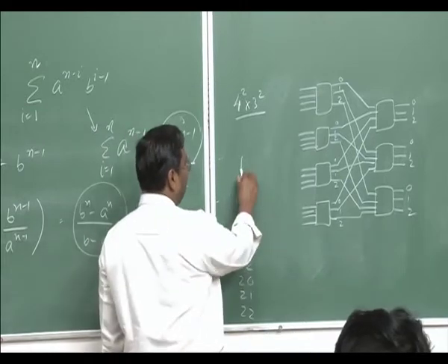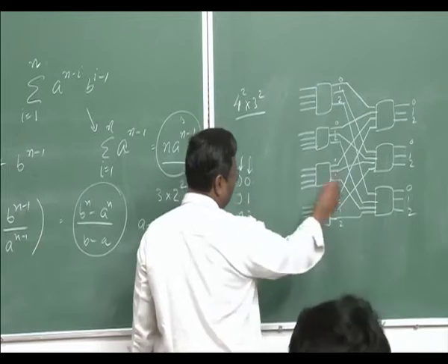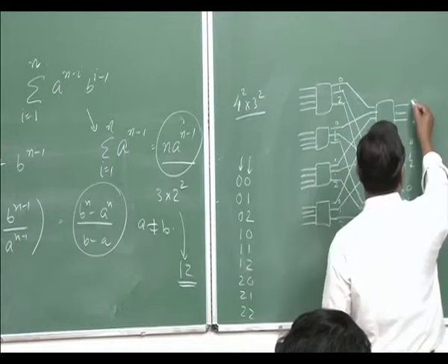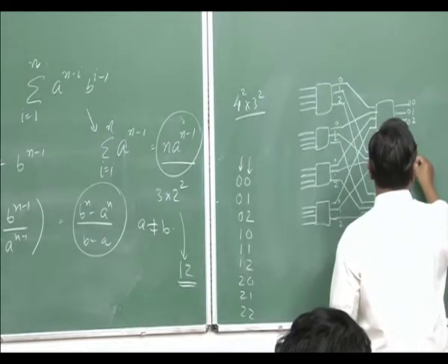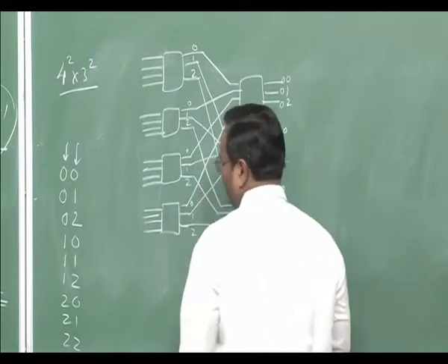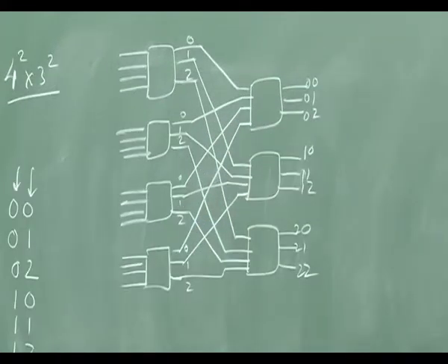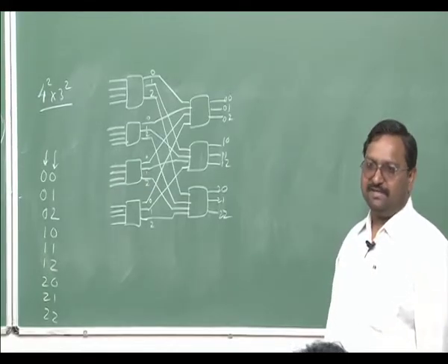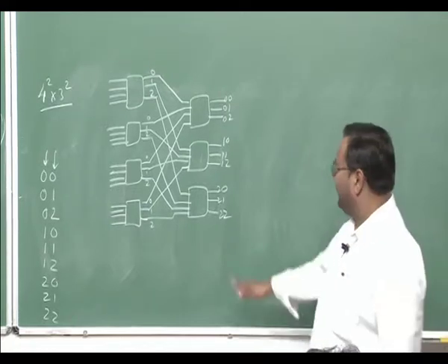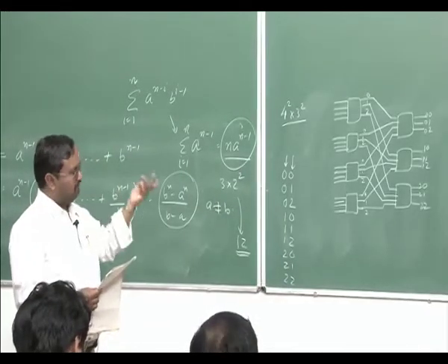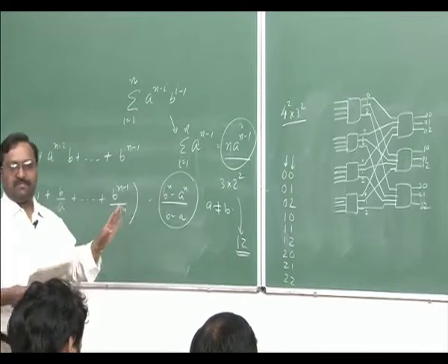The first digit will be used for routing in the first stage, the second in the second stage, and you will reach the destination. So, these will be the numbers like 0 0, 0 1, 0 2, 1 0, 1 1, 1 2, 2 0, 2 1 and 2 2. You can build any kind of complex thing with this kind of structure. Make sure you make a demultiplexer tree every time for every input which you are going to connect, while maintaining the same condition. Of course, in general there can be many possible ways you can create it.